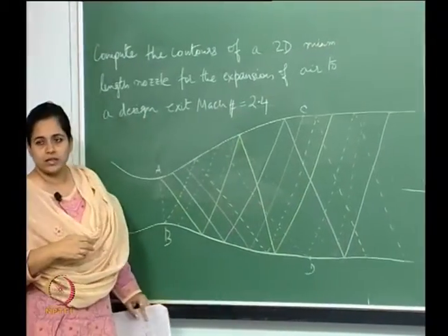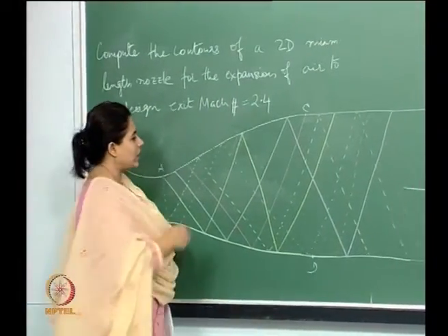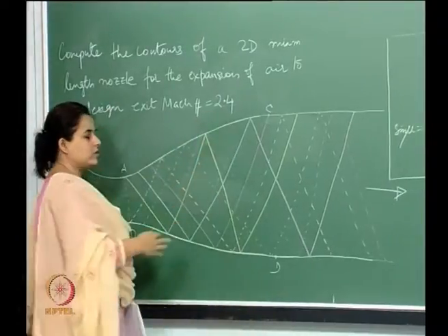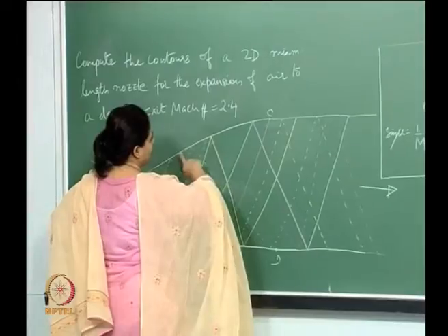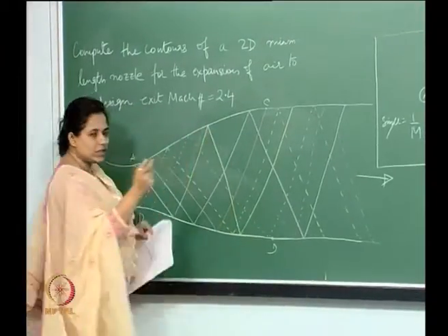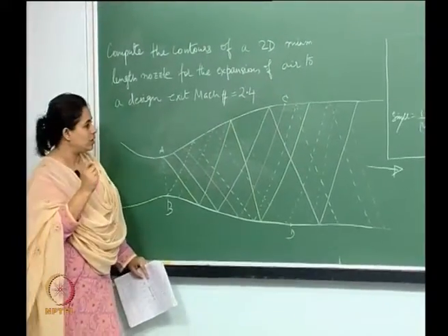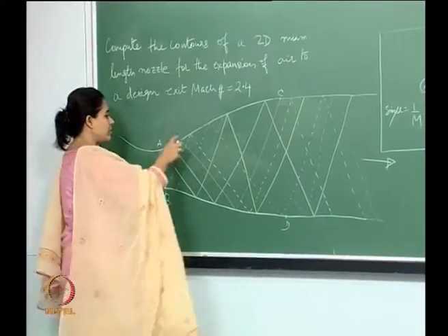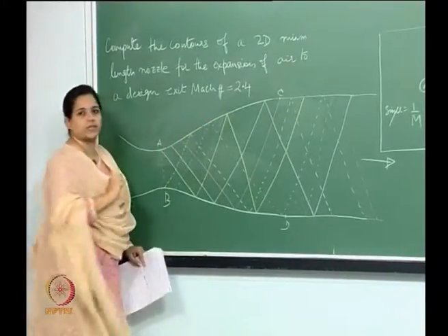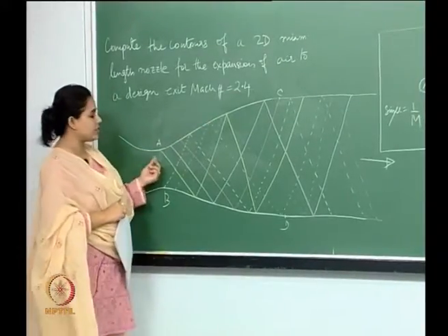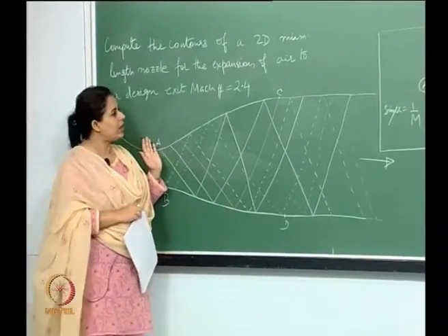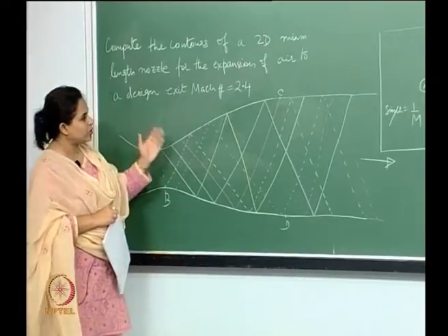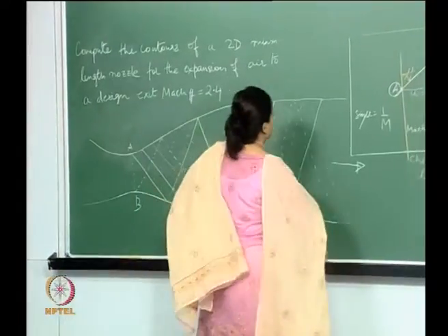We want to decrease this expansion region, okay, basically the non-simple region. So, in this non-simple region we can decrease that to a certain point. Okay, so that this becomes not just a spread out expansion fan like that, but a centered expansion fan. It will expand only at a particular point. So, when you have that, then let us see what it looks like. Okay, let us do that.